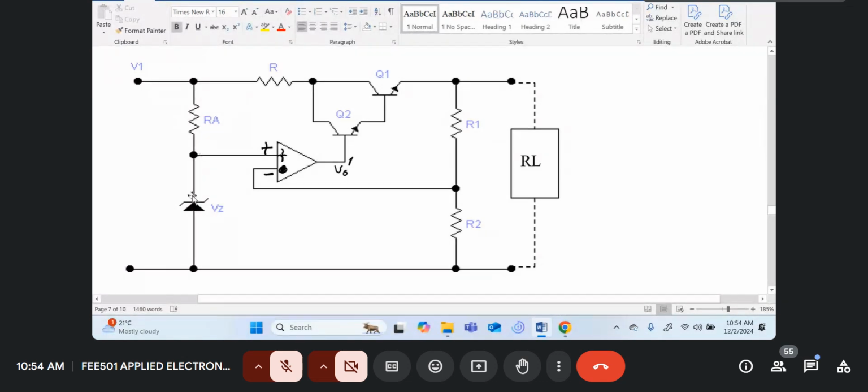You've got a reference circuit over here, which comprises this resistor RA and VZ to give us a reference. Now the difference here, the reference voltage is connected to the positive of the error amplifier.